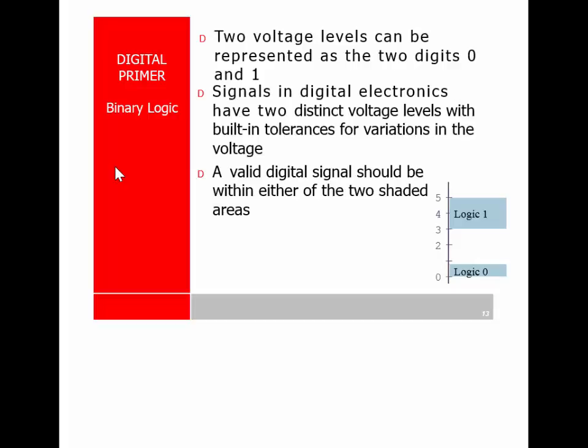devices out there. As electronics get smaller, and in particular digital electronics has gotten smaller and smaller, there's been an effort to reduce this voltage in order to reduce the size of the components, particularly the capacitors for filtering and things like that, and the gate width. We're not going to talk too much about that, but it's the physical characteristics of how these ICs are made that they now require less voltage. So 2.7 volts to 3.3 volts is pretty much a standard today. But the key thing here is that you've got a region that is high, and a region that's a